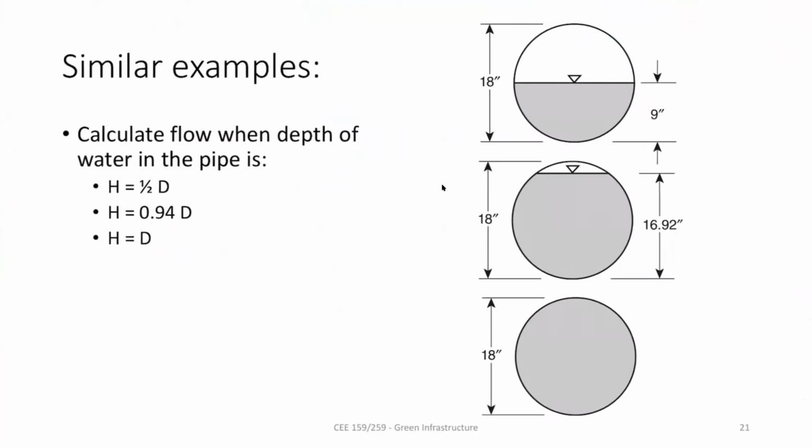Also, pressure depends on wall inclination. If you have this straight wall versus this wall, the pressure will be very different. In fact, it is more stable to have this kind of inclined wall. That's why you can see this big dam has a shape like this. They don't create a vertical wall, just to avoid that pressure. So this is just an example. Vertical wall: what is the pressure?